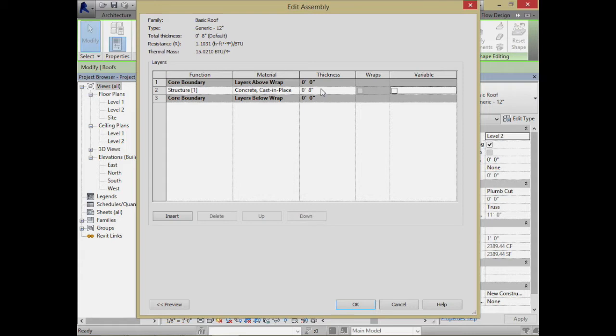Often, one thing you want to do with your green roof is you don't just want to put plain old grass up there that you have to run a mower up on all the time. So it tends to be very natural, local, sustainable materials that will hopefully grow. In fact, when we talk about green walls, it's going to be the same sort of issue. You don't want to put a high maintenance surface up there because people aren't always so good about maintaining their lawns. So, we want to keep it easy. So on top of this, we're probably going to have some different layers of things. If you think about the section of a green roof, what tends to happen is you'll have the structural layer. You typically don't just have the earth, that wet earth sitting right on top of the structural layer.